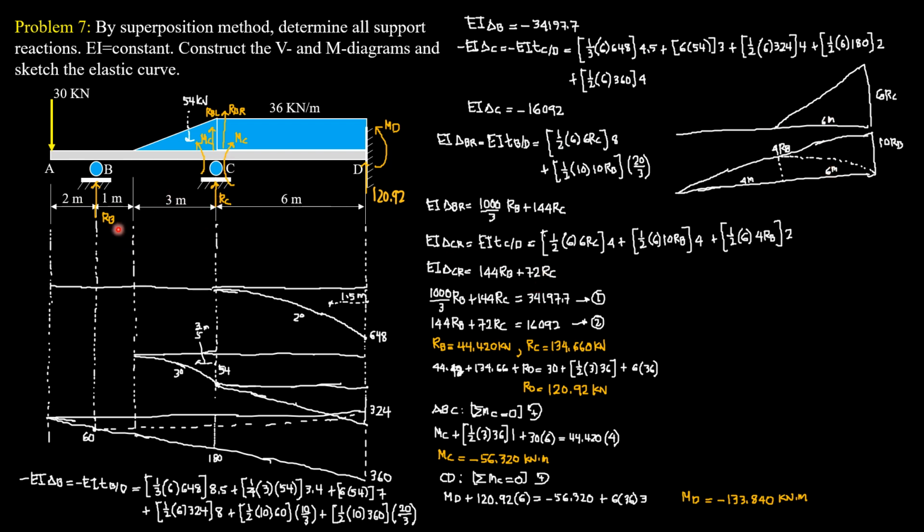So these reactions will cause the cantilever beam to deflect upwards like that. So if we compute the deflection at B, which is positive this time, due to the reaction at B, it is just the vertical deviation of B relative to the tangent at D, interpreted from area moment principles, as the moment of areas between B and D with respect to B. So these are the areas, and for the first area here, 1/2.